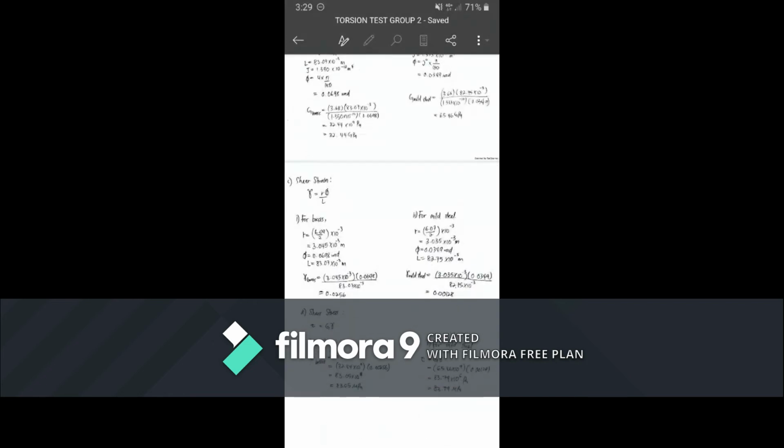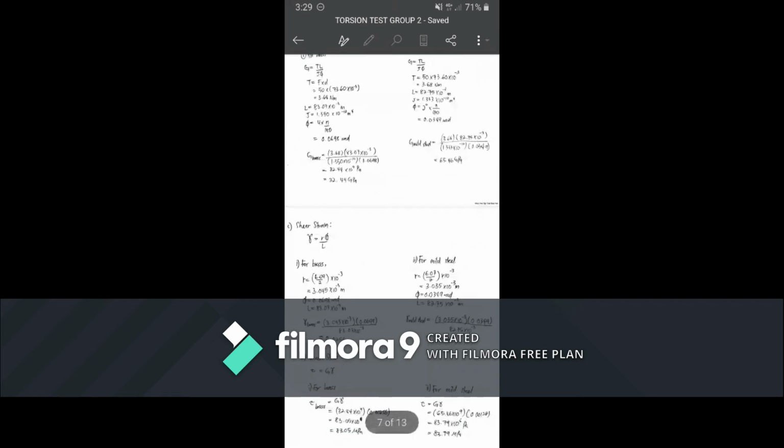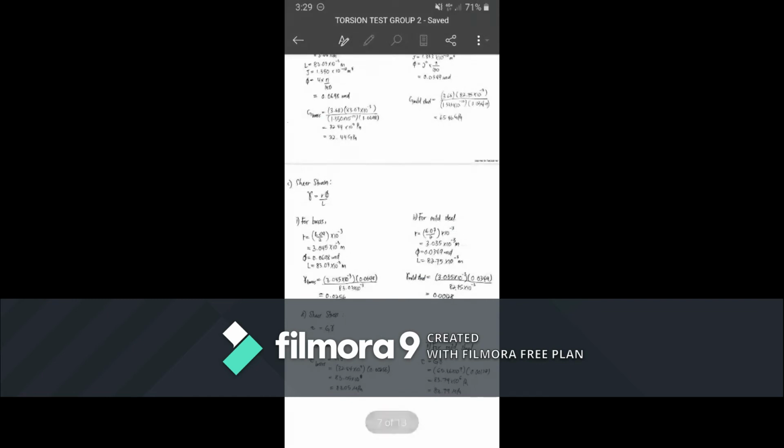So the next thing is we need to find the shear strain. By using the formula R angle of twist over L, we will find the shear strain. For brass, the radius is 6.09 over 2. 6.09 is the diameter, so for the radius we divide it by 2. And then for the angle of twist, we get it from the above calculation. The length is given, and after we get all those values, we insert them into the formula, and we will get the answer.